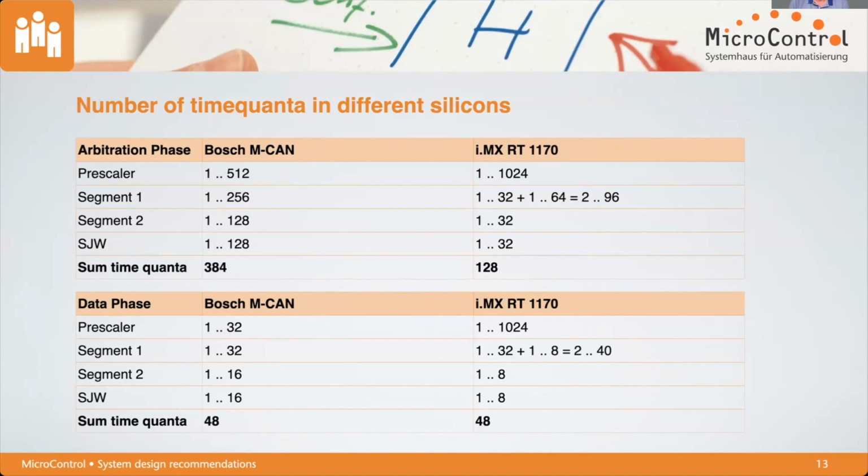And if you want to run the system with a 40 megahertz clock, we will later find out that you can't set up the bit timing registers with the desired prescaler and the desired bit timing values in that specific controller. So some silicons are really limited. Again, I repeat what has already been said today: please be wise in your decision of the silicon that you choose.